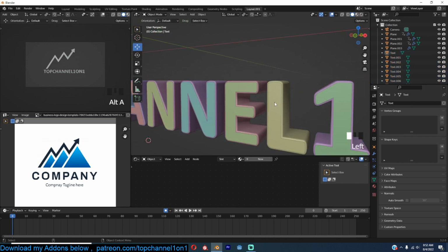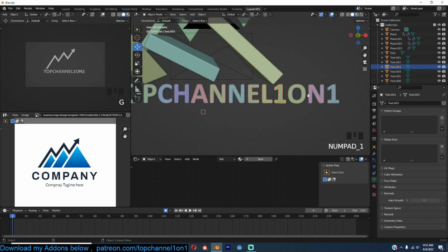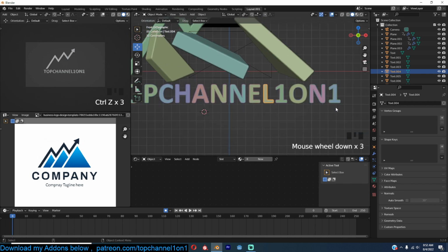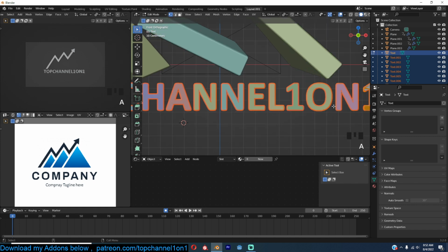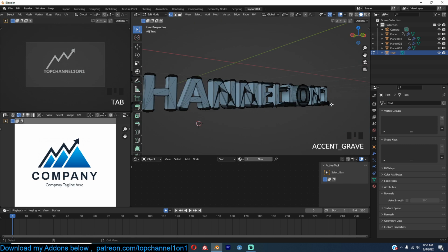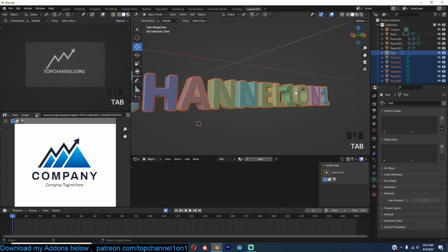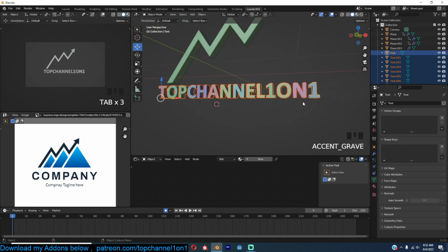that you have more parts than you expect. So maybe that's what you want, but for this that's not what I'm going for. Make sure that every letter is a single object. All you have to do is go into edit mode, select all the points, and then by using Ctrl A and then hit M, then merge by distance like that, and you see that you have removed quite a lot of vertices. And now if we go back and hit P, separate by loose parts, you can see now we have each letter as an individual letter.